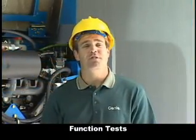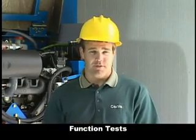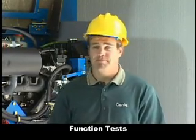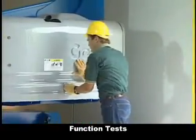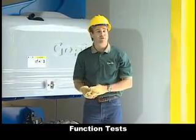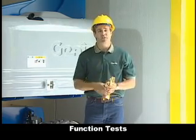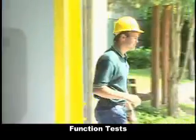And why do we do function tests? Well, that's to make sure that you can get up safely and get down safely before you go into the work environment. We want to discover any malfunctions before the machine is put into service. Of course, you have to get up in the air to do your work. But more importantly, if there's an injury or something happens and you need to get down, or others need to bring you down, it is vital to verify the machine is operating properly.